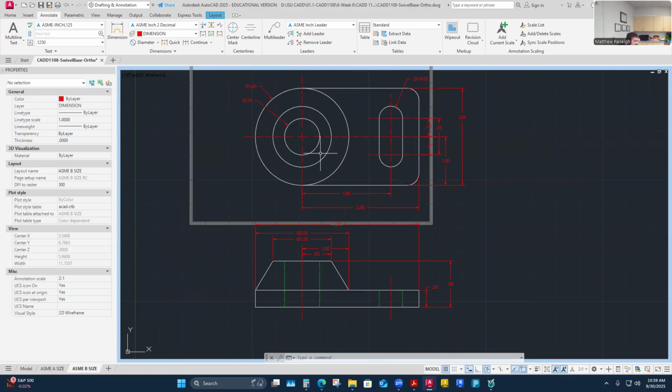And that's what I'd really like you to try to figure out at the end: if you analyze your parts and where dimensions are being pulled from, do you have one, two? Generally, you're always going to have at least two control points. Do you have three? Great. If you keep adding up, pulling from 5 and 6, you've complicated how you're pulling your dimensions. You should probably target about 3 control points.